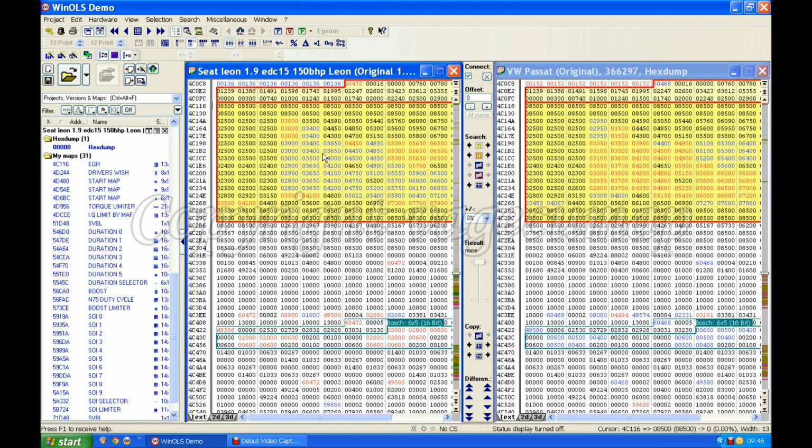Now, at this moment in time, I'm not going to worry, because I really don't think that I can prove anything by looking at these two EGR values, because, as I said, they are more or less the same. So as far as I'm concerned, the EGR map on a PD 130 and a 150 is probably not worth fiddling with. If I was to try to do any kind of remapping work, it would probably be simpler to just leave them as they are. So in other words, this one would be good enough.